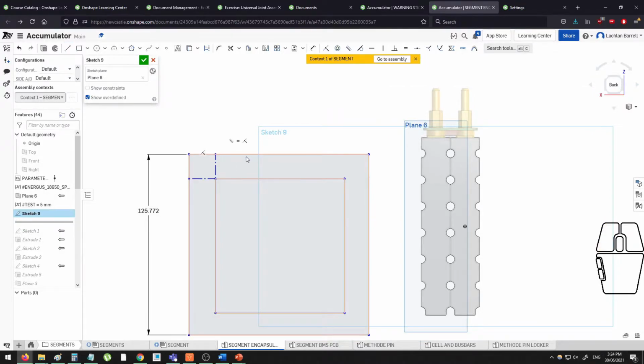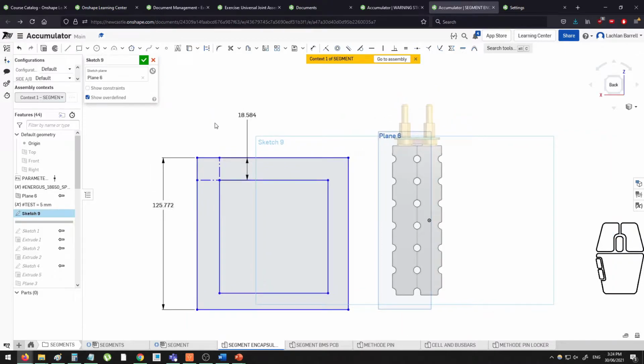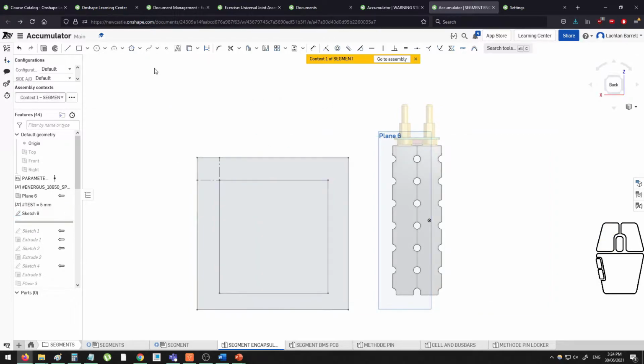Wonderful. And then I can actually set those two construction lines to be equal and dimension them as needed. The potentially smarter approach, if you're using certain dimensions all over the place and you need to set a whole bunch of things equal to that dimension, is to use variables, which I end up talking about a little bit later on in another video.